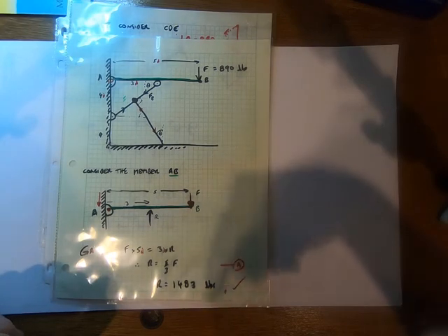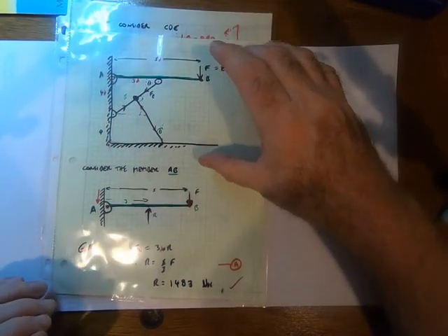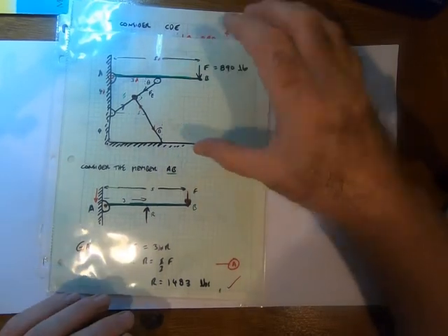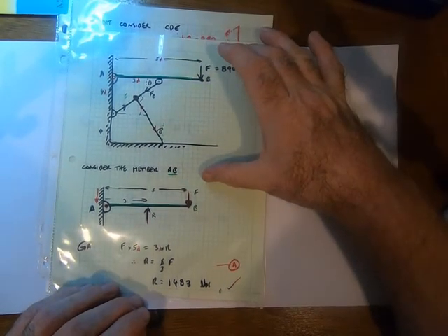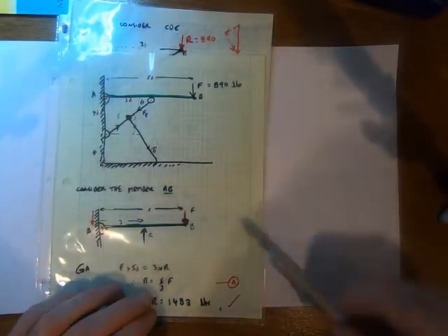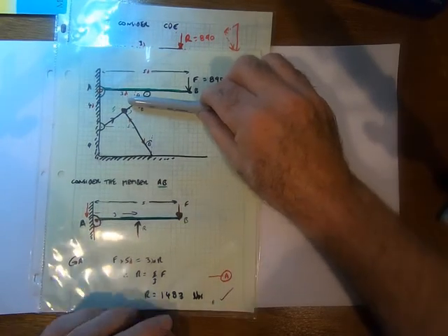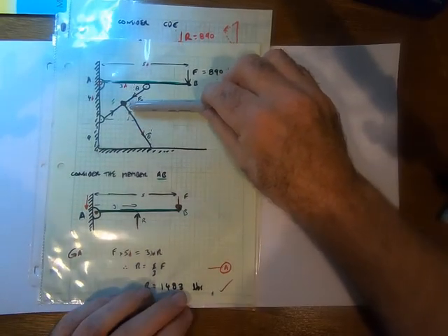It's getting you back thinking about big sketches. Draw all the forces and dimensions that are relevant, any angles, all the information you've got, put it on a nice big sketch to begin with, and then redraw the subcomponents. Students quite often will do the one sketch and then do the analysis on that one sketch. I can't stress enough how important it is not to do that.